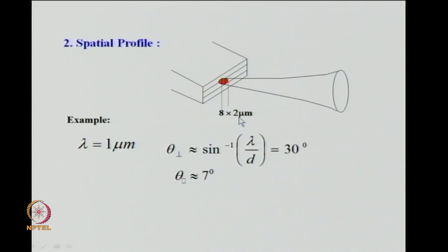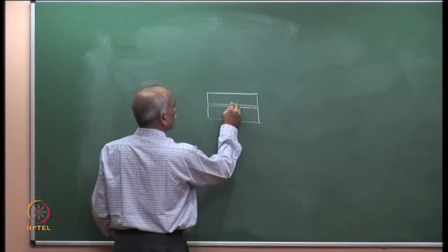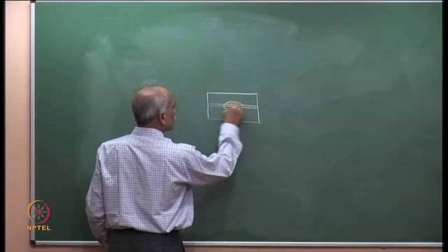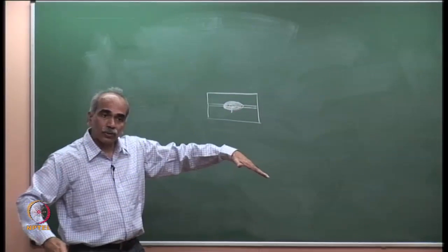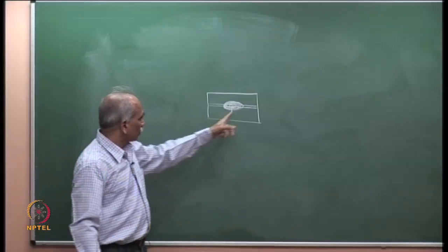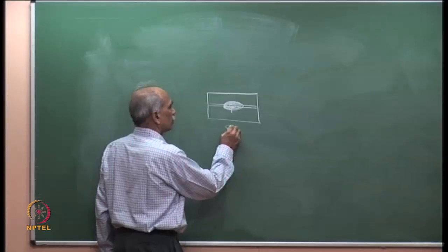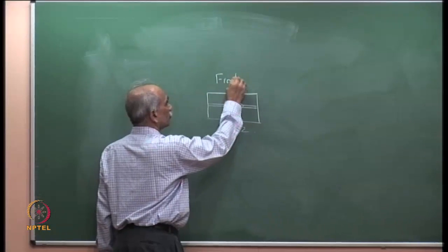This is not the physical size. Please remember, the double heterostructure, if you see the front view, had a layer which was 0.2 micrometer here. So, this was 0.2. But the laser spot which is generated, because the field is spreading into the cladding also, there is an evanescent tail. So, the spot size is generally about 8 by 2. So, 8 cross 2. This is the front view.